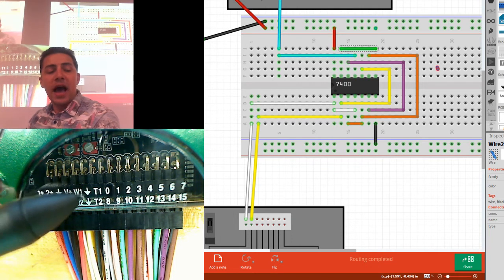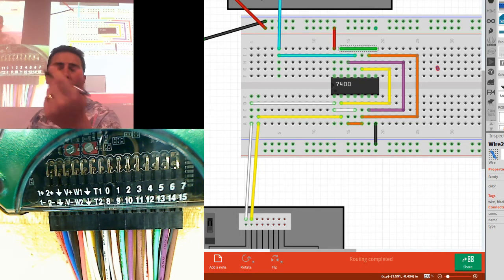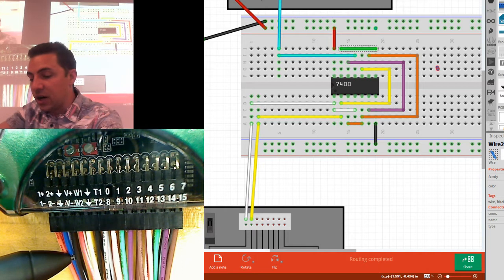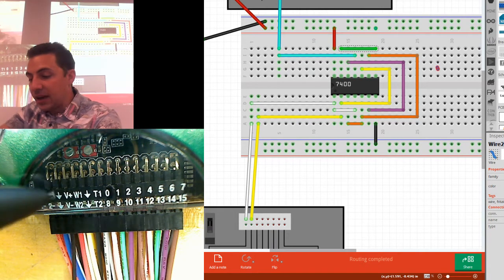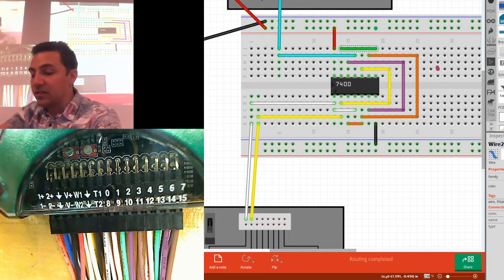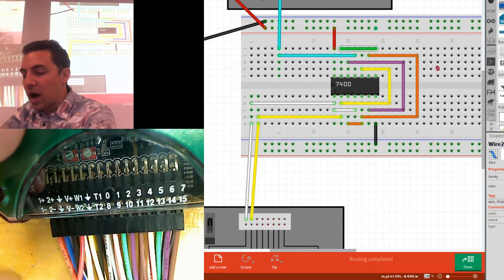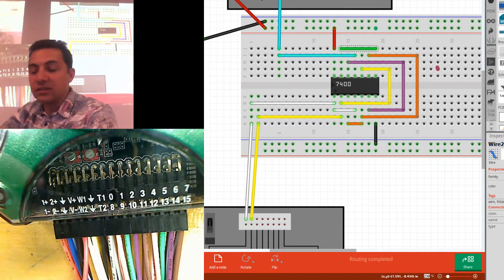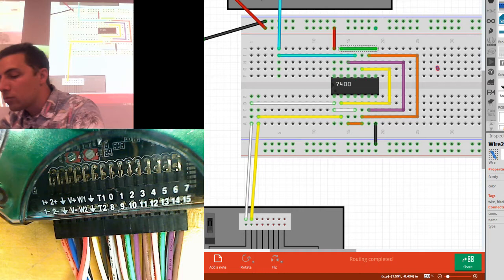Every one of these down arrows, which I think lasered into those, it just says V. Those are your grounds, and they do follow that convention of the black wires are ground. The next row over is V plus and V minus. There is a red and a white wire. Red is positive 5 volts. White is negative 5 volts, and I'll show you those power supplies in a second.